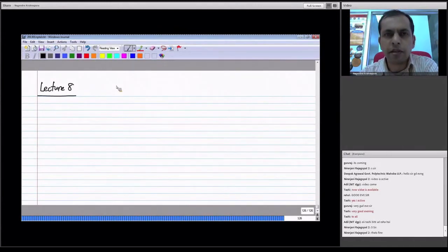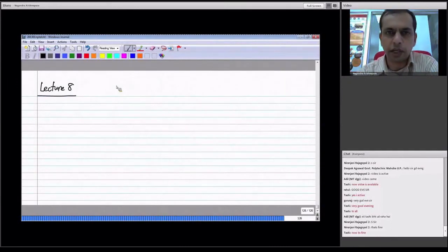Okay. So in all the cases, on the right hand side, you have the source vector, which consists of independent current sources and independent voltage sources. And on the left hand side, you will have a matrix times the variable vector. The variable vector will be the node voltages with respect to the reference node plus any auxiliary variable you may have used. If you have voltage sources, there will be the current through the voltage sources. Okay. Now, before we go on with today's lecture, if there are any questions on previous lecture or any aspect of nodal analysis, I would like to take them up.